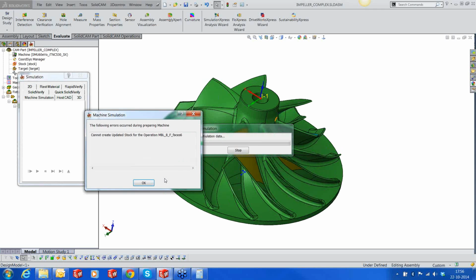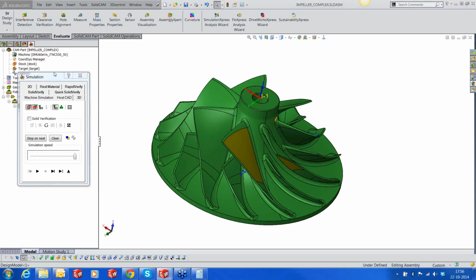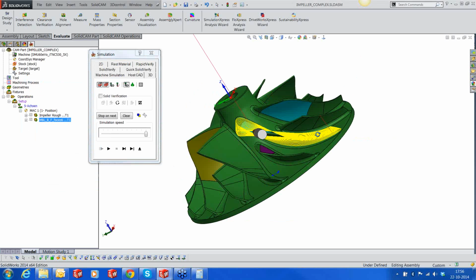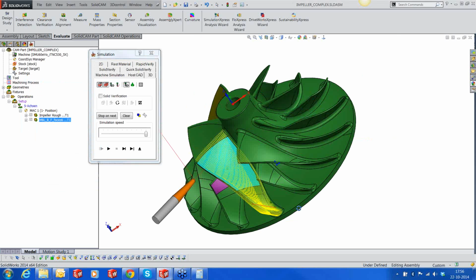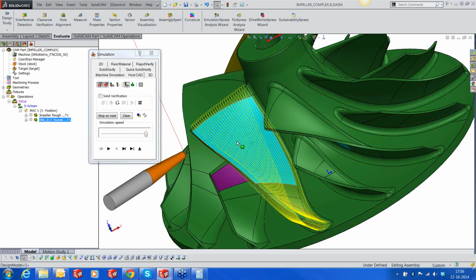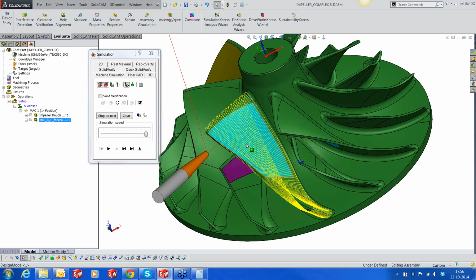Cancel, sorry. You can go into the host CAD and show you the finishing. So you can look at the amount of parameters that I defined for our toolpath definition. It was bare minimum. I had to just pick the blade, just put in the depth of cut, pick the tool, that's it. The toolpath is generated by itself.